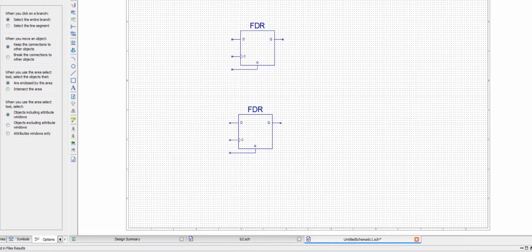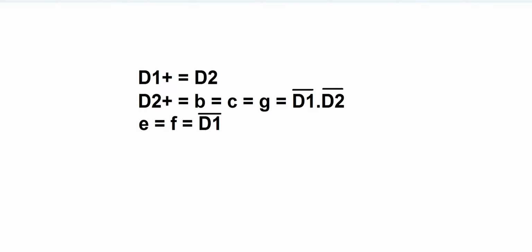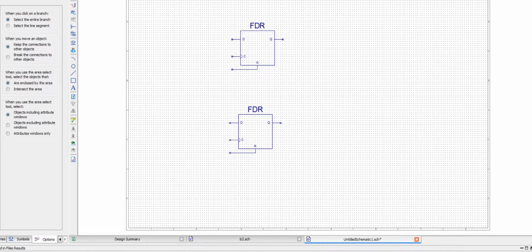The thing is, these logic equations work properly, assuming that when you turn on your system, inside both of these flip-flops is 0, so the system is at state 0 0. But sometimes when you turn on your system, there can be a 1 in one or both of the flip-flops, and that may cause problems.